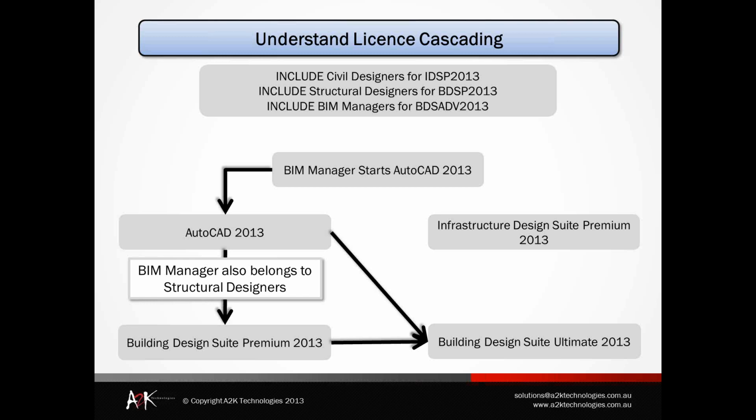Right, so just having a look at the License Manager, the current version of the License Manager for 2014 is 11.11, and we've got a hyperlink there also on how to configure LM tools. Some of the key things I think for IT here, apart from understanding how to configure LM tools, which is outlined in the hyperlink, is the understanding of how the IPv4 and IPv6 affects the License Manager.